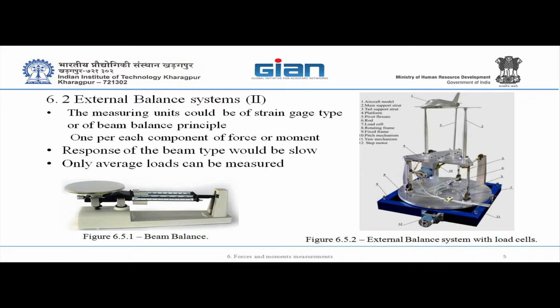this is good if you take an aircraft from the supersonic or transonic tunnel, which is 1 to 15 scale, and you go to the low speed, they take the same model, so no problem. But if we have to measure forces for business jets, which is 1 to 5, 1 to 6 scale, 70% of the test section, it's a huge one. You cannot hold it with a sting balance. Still, you get only static measurements. So for business jets, we cannot use the sting balance because the capacity may not be enough.